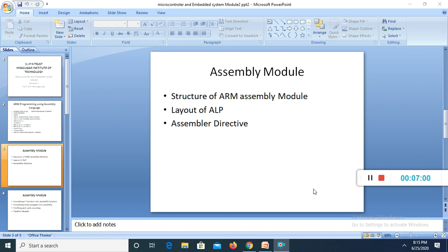The FILL directive reserves a block of memory to fill with a given value. The DCB directive allocates one or more bytes of memory and defines the initial runtime contents of the memory. Then DCD or DCDU. The DCD directive allocates one or more words of memory aligned on 4-byte boundaries and defines the initial runtime contents of the memory. DCDU is the same except that memory alignment is arbitrary.